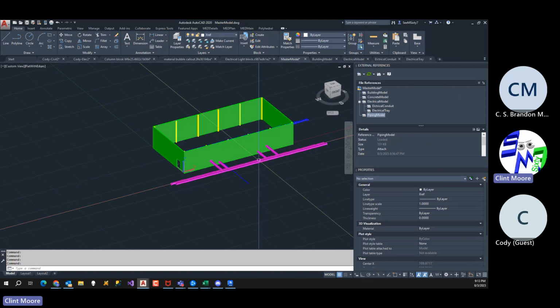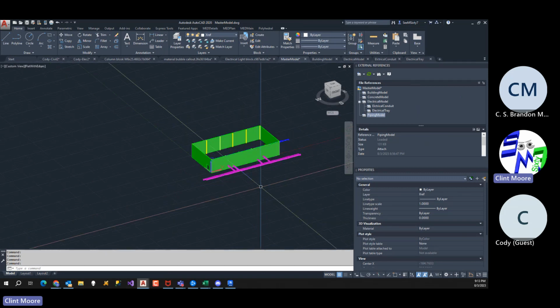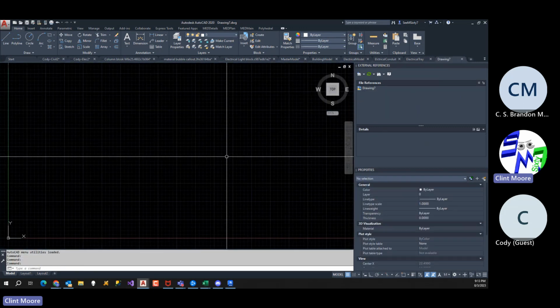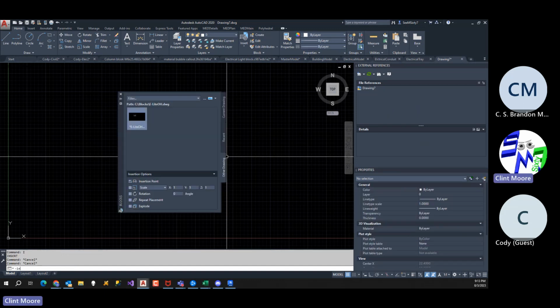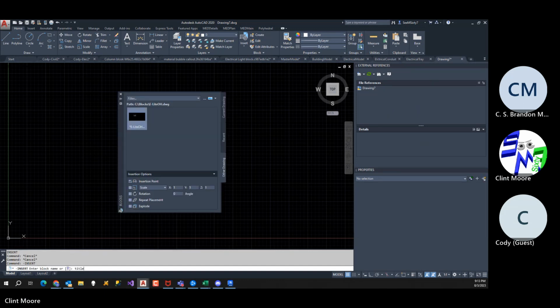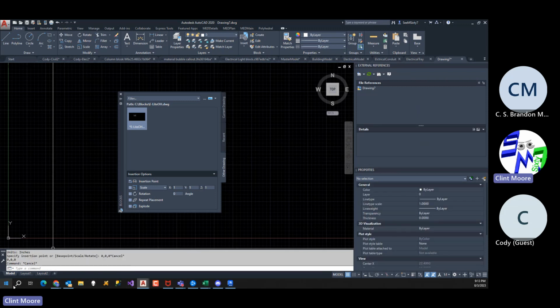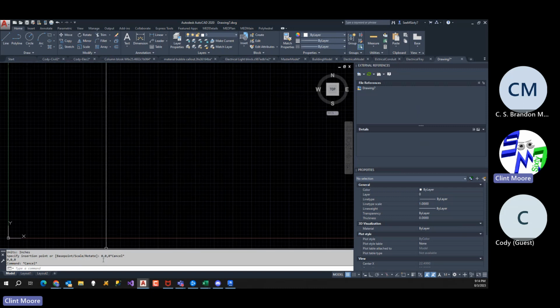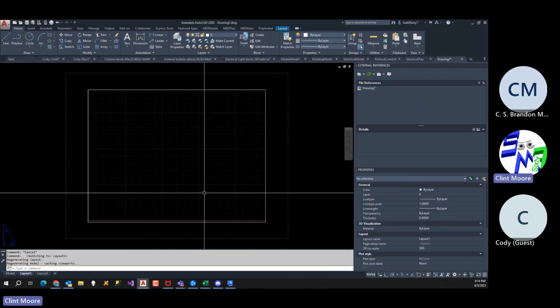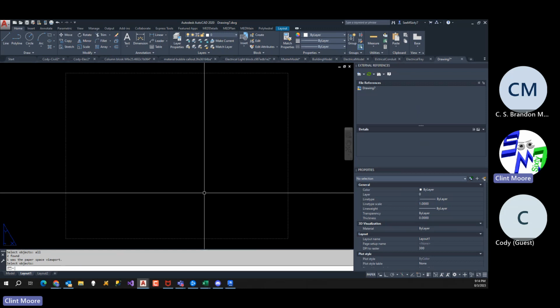All right, so before we get too far along, I want to actually go ahead and start a drawing with a title block, okay? And I'm going to click here. We're going to do insert. Oh, we actually do dash insert title. Then we set that as 0,0. Oops, actually I'm in model space. I want to go to layout mode right here. We go to layout and erase all. That's the default viewport that comes in.